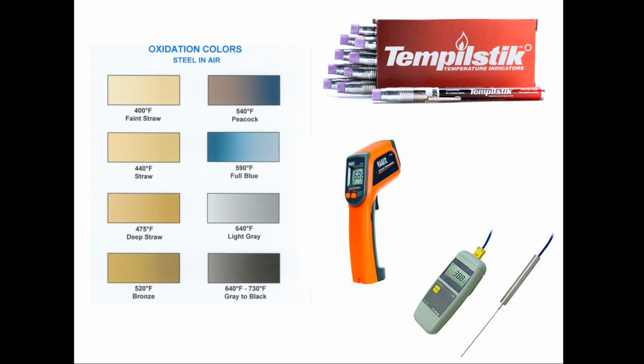We need to make sure that we do a little bit of drawing back from hard, right? Old term again, or tempering, or some materials want a double drawback from hard. You might look at your procedure, and your procedures will tell you everything. Every company, Eutectic, Eureka, all these different companies that make tool steels, all have procedures written out in books. We're going to explore a couple of them very soon.